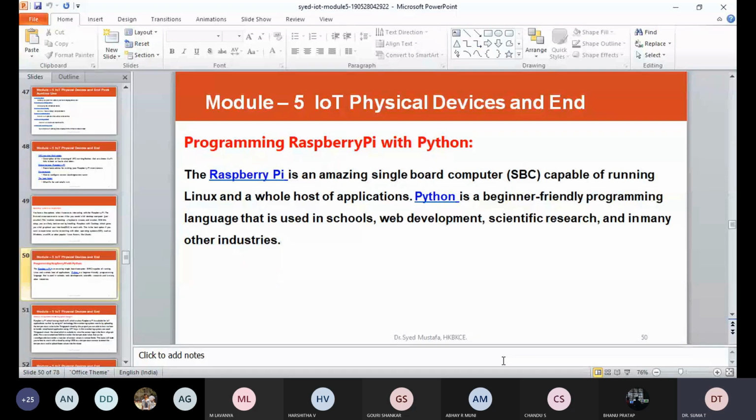Okay, so I wanted to share some of the commands with respect to the Raspberry Pi, right? You have raspi-config. These are the general commands for your Raspberry Pi. raspi-config is our configuration settings menu, and if you do clear, it clears the data from the terminal. Whatever the previous execution is on the screen is going to be cleared. Date displays the current date.